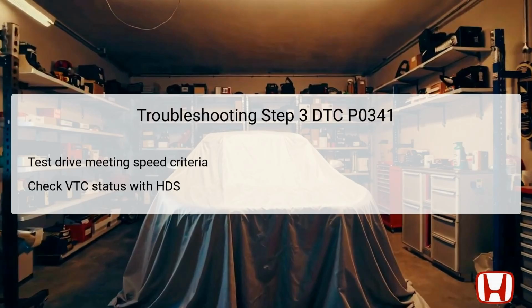If the values do not align, repeat the test drive and recheck the VTC status. Ensuring consistent performance in the VTC is crucial, as deviations here can directly affect how the CMP and CKP sensors operate, potentially leading to the triggering of DTC P0341.